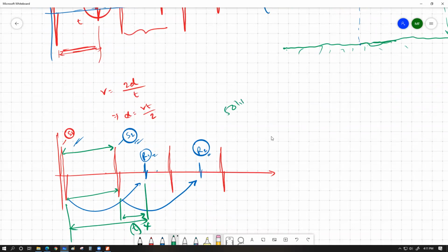whenever we are traveling to deeper water, we should prefer to send at maybe 50 hertz, because if we send at 50 hertz, this send pulse would be missing. We have this wave, we wait double the time, so we miss out this pulse, and we send another pulse over here. Then we get the reflection of this sound right over here, and this reflection would not be here, and this send pulse would not be here either. Rather, after a really long delay, we get this reflection, which is for this wave, and then we send out another send wave just like that.